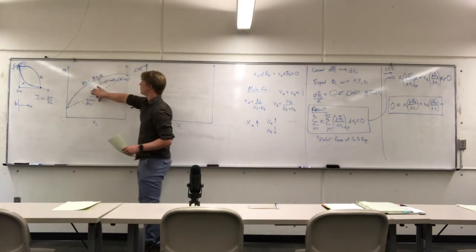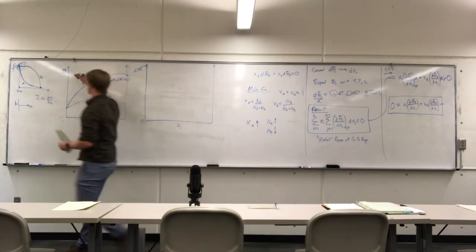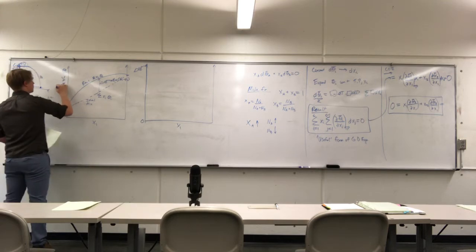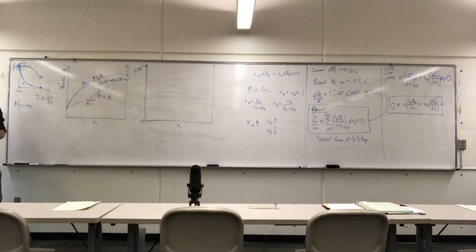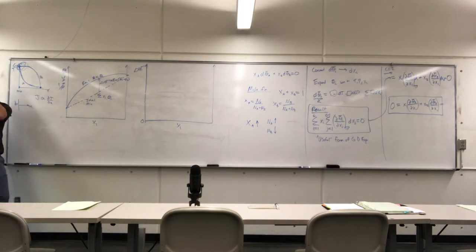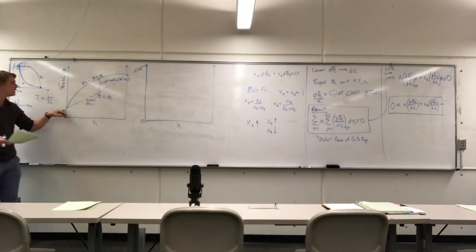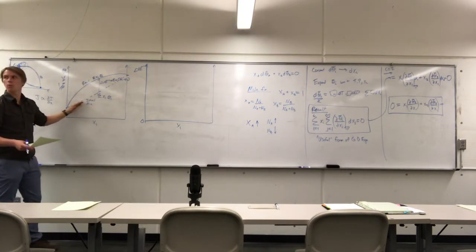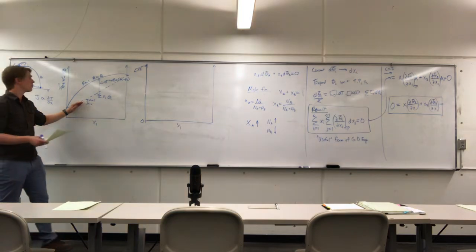Now, if I represent this set of measurements here, this could be, for example, let's say this is specific volume, or reciprocal of density. So what I'm doing is I have a densitometer or a pycnometer, where I put the fluid in the densitometer. It either is a U-shaped, vibrates, and gives me a number, right? I plot it out. I can do a weighted average, assuming ideal mixing.